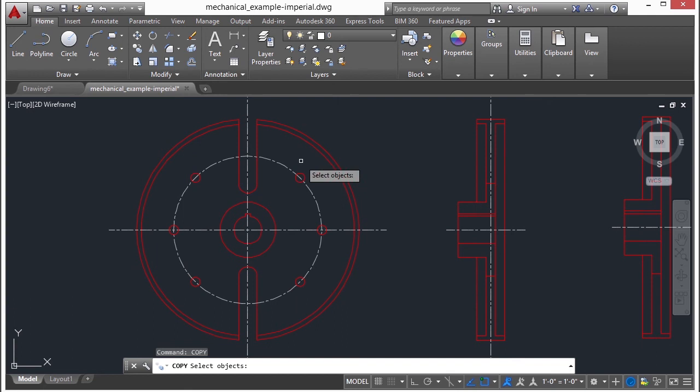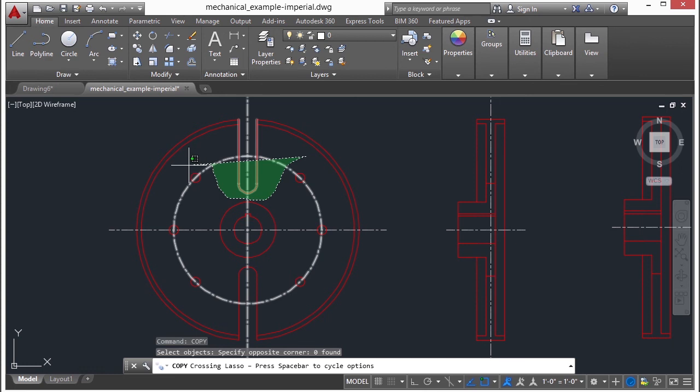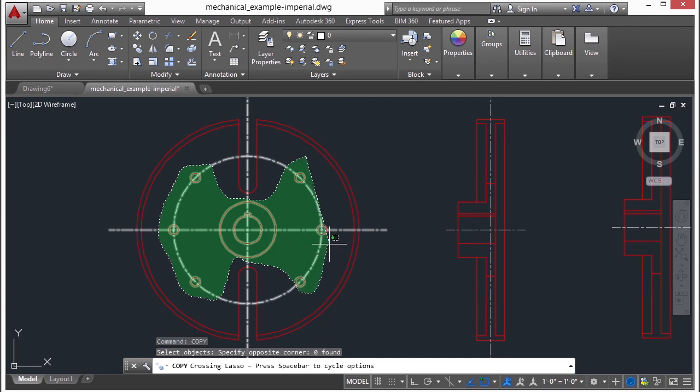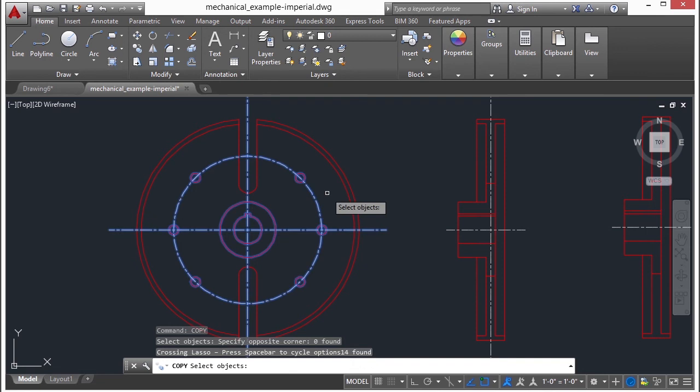And when I do my crossing windows, now you select an open space somewhere and let go of the button and you drag left or you drag right. You can press your left mouse click button again. That'll end that selection. But this time what I'm going to do is I'm going to left click and hold. I'm not going to let go of it. I'm still holding it down and I'm moving my mouse. Everywhere I move my mouse creates a selection window, but it's like a polygon here. It's a weird amoeba shape, and it's only going to get the items that I select inside there. And I let go, and just those items are selected.